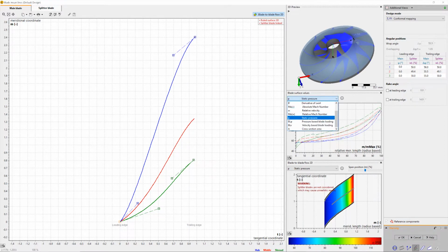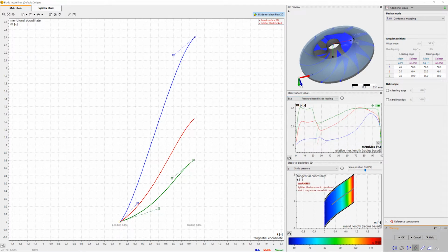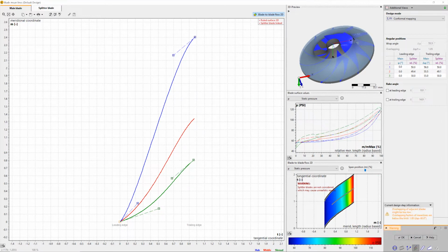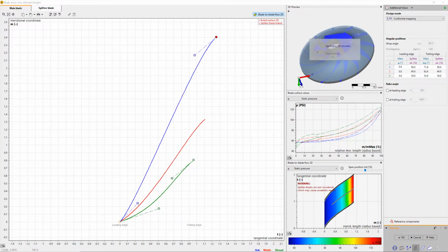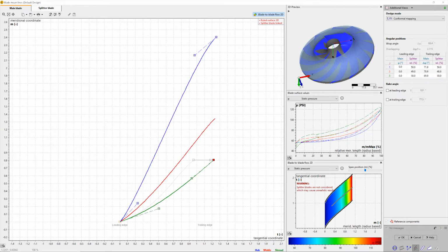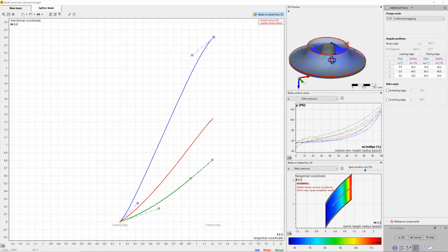On the right side of the window, there are options to configure various diagrams and geometrical views to evaluate the blade design. Blade-to-blade calculations and blade surface calculations are based on the Stanitz-Prien methodology. Among others, we can select estimates of Mach number, absolute and relative velocities, pressure, swirl, and blade loading. A real-time 3D view of the blade directly shows the modifications in three-dimensional CAD. In general, the user can choose between direct beta distribution, M-theta conformal mapping, or inverse design by blade loading for centrifugal compressors.